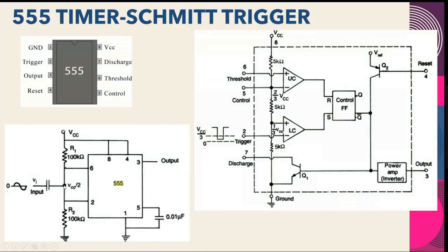How can we find this voltage? The total voltage is VCC into the same-branch resistor divided by the total resistance. So if all the resistors are the same, I'll write it here: VCC into R divided by 2R, R will get cancelled. So this voltage will be,